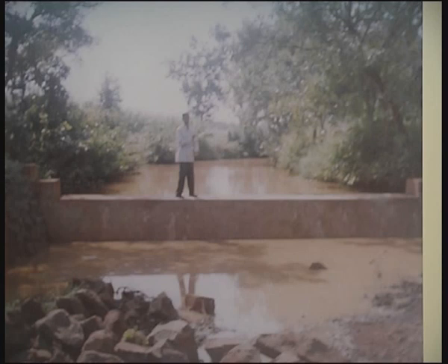The entire emphasis is for recharge structures in the upper areas, in the uplands, and any recharge occurring very near the ridge boundary of the watershed would result in increasing the water table levels in the ridge areas and upper areas, which in turn would lead to increasing the groundwater availability in the lower areas as well.